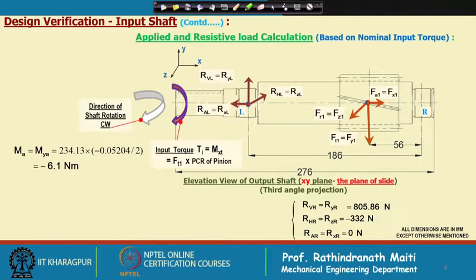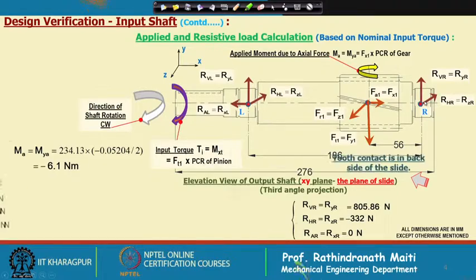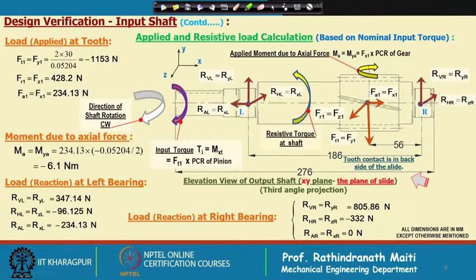On the input shaft, as we find, input is from the left hand side, direction of rotation is given, torque is given, and then the loads on that shaft that are coming over there are also shown here. At this stage I think all the total loads are shown here. So, we have considered all loads on the shaft, right.